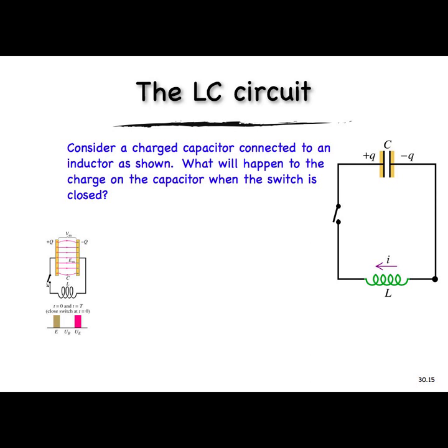This little indicator right here is the trigger. It's going to freeze the oscilloscope display anytime this current, or this voltage exceeds this level, which it's not doing right now. But if I allow current to go through, and then I break that current and give it 3 seconds to refresh,